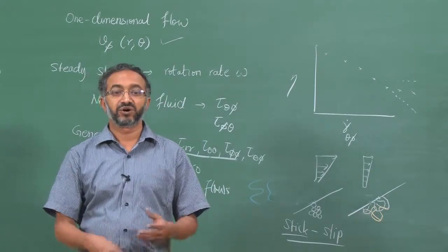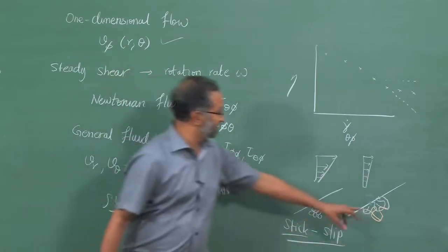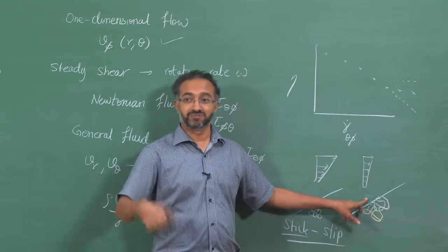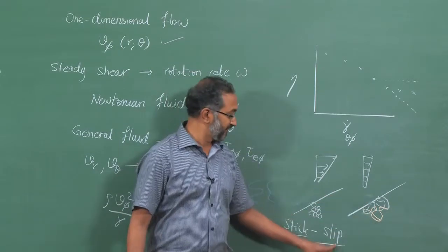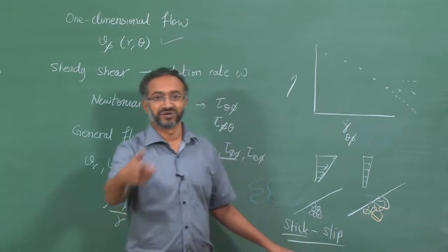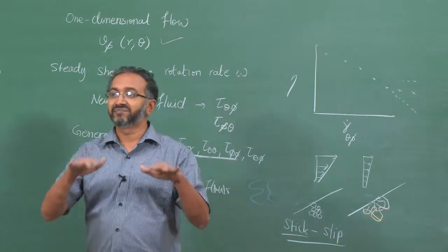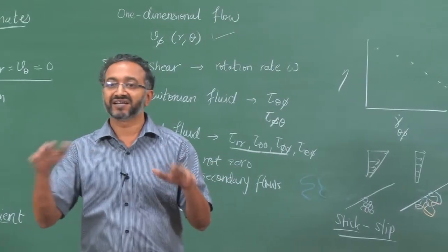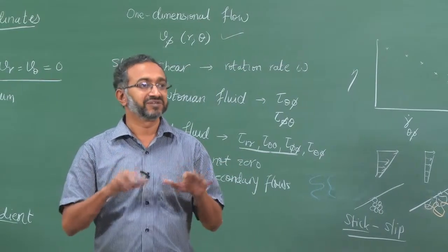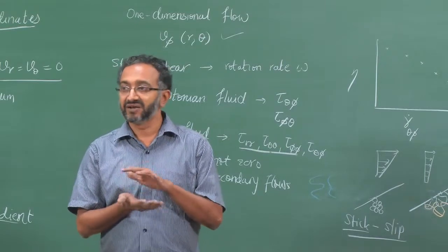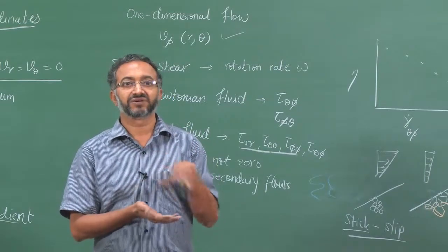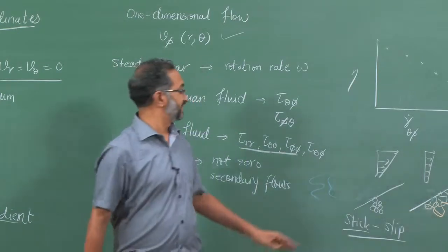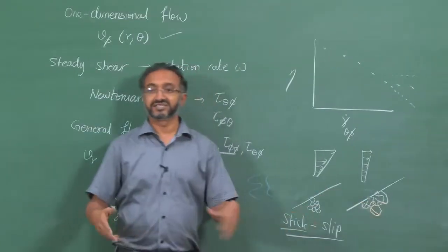Because in this case I know that the polymer does not adsorb very well, let me now go to a surface where adsorption is even poorer. Then I am saying that slipping will be even more. So, anytime I do measurements with different surfaces and I measure different viscosities, I clearly know that something is wrong, because a material property should not depend on the surface of the geometry. So, quite often we modify the surfaces and then check.